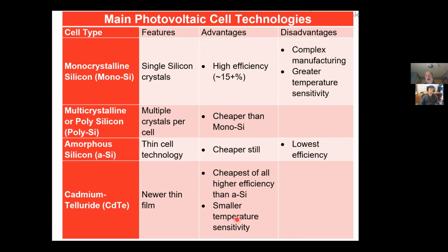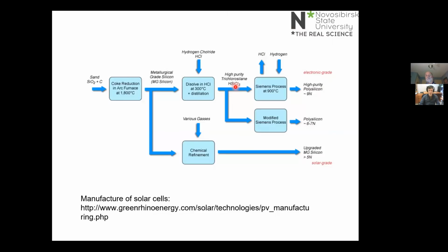It's going to come down to maybe there are situations when the high efficiency is important. You know, maybe if you're going to put a PV system on the roof of a building, then you're limited in space. And so to get the maximum power output from that, you could choose a higher efficiency module, even if it is more expensive.